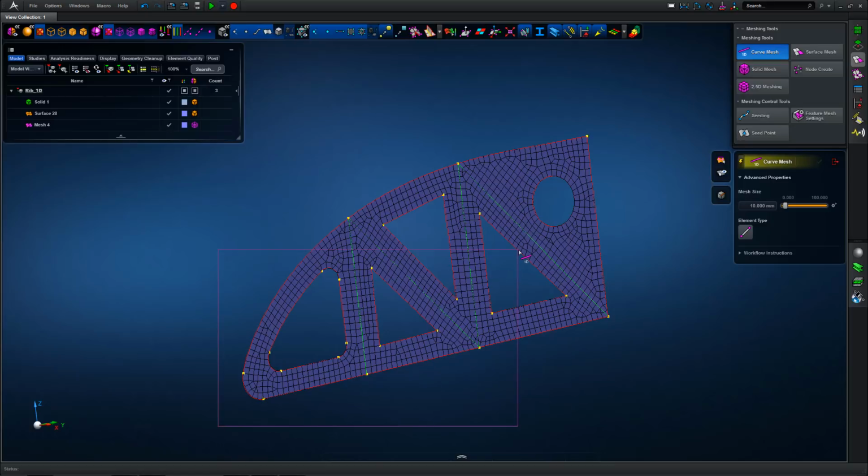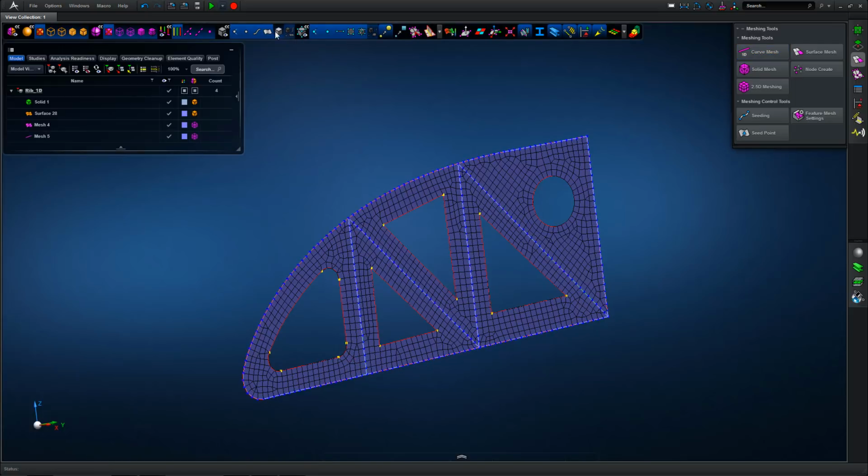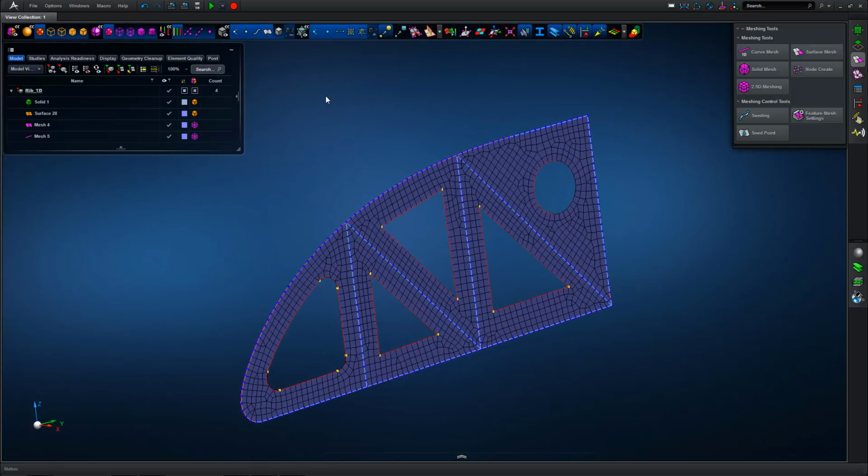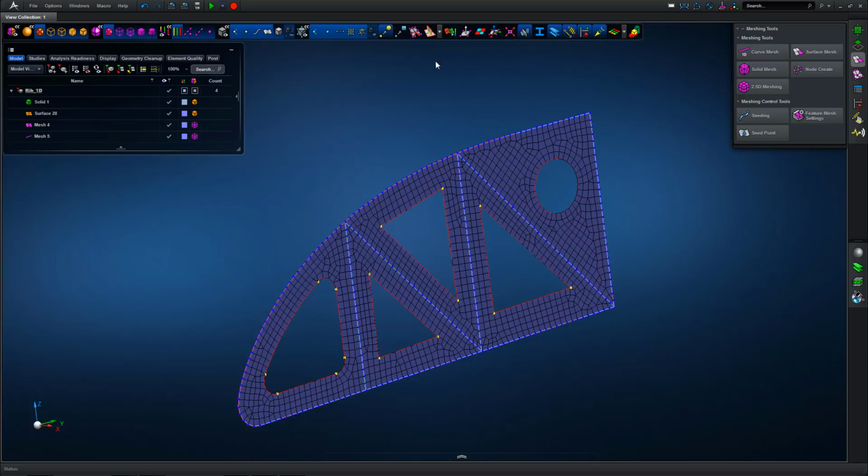Okay, so with the 2D mesh defined and controlled, we're now into curve meshing. We could enter an element edge length, but because we're meshing the edges and internal curves of the underlying rib surface, it will take the 25mm underlying edge length accordingly. So it's just a case of a sweep pick to pick all the curves, obviously removing the curves from the lightening holes that we don't want, and we can see the curve mesh generated on screen.